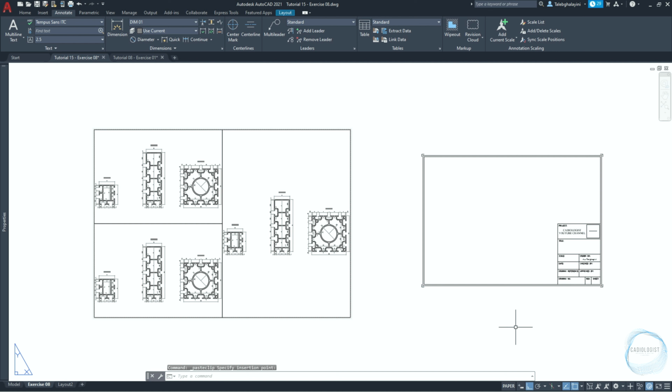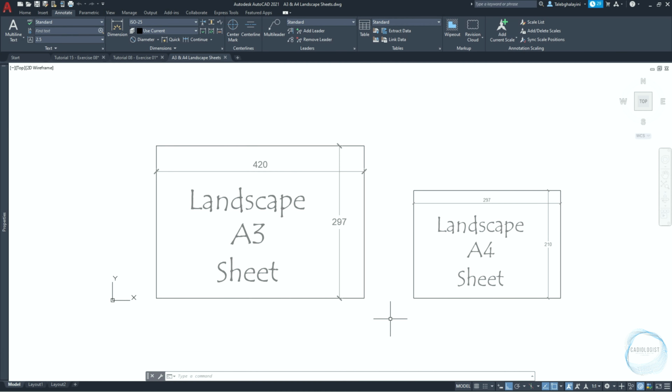If you can remember, I created this title block in Tutorial 8 for A4 sheet. But in this exercise, I want to print the 3 aluminium profiles on A3 sheet, so that I have to scale the A4 title block to the size of A3 sheet. The scale ratio in the X direction will be 420/297, and the scale ratio in the Y direction will be 297/210.